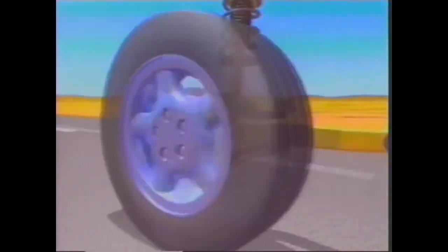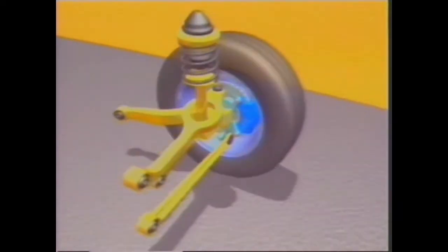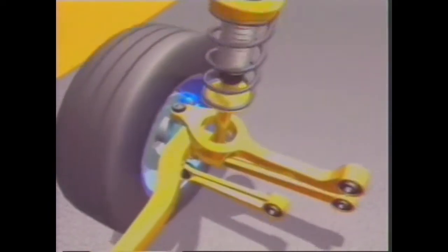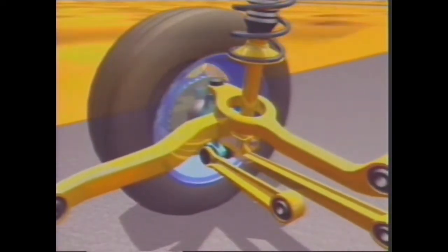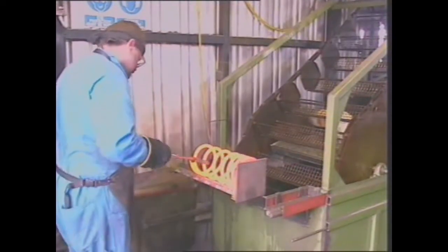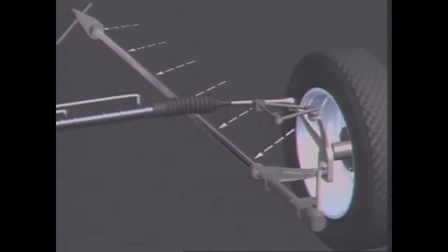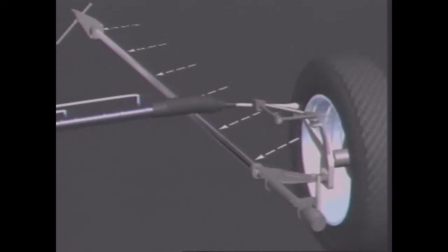Automotive suspension systems generally use the elastic properties of metals to provide the springing medium. The springs are located between the frame and the axle assemblies and are shaped to suit the application. Leaf springs are normally semi-elliptical, and they absorb the applied force by flattening out under load. Coil springs are formed in a spiral from a single steel rod and absorb the force of impact by twisting. Torsion bars are held rigid at one end and twist around their center as the suspension arm is deflected. They all return to their original shape when the deflecting force is removed.